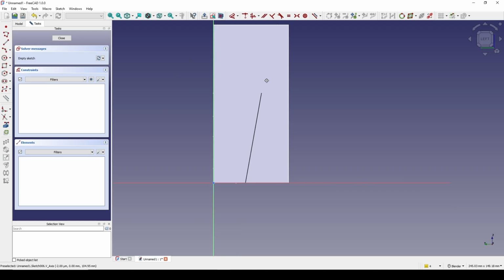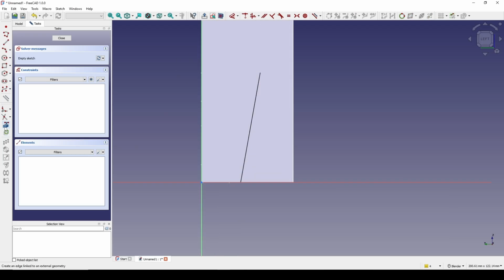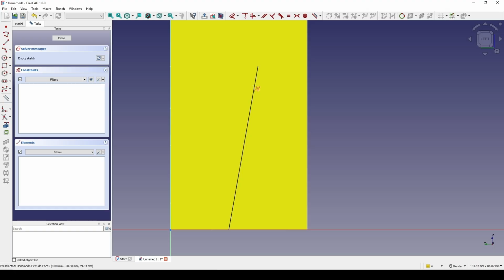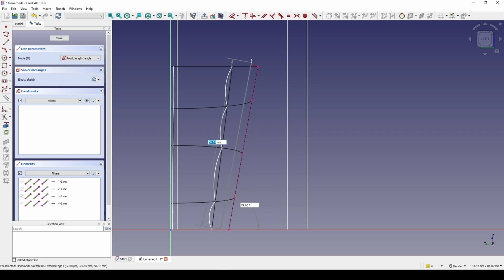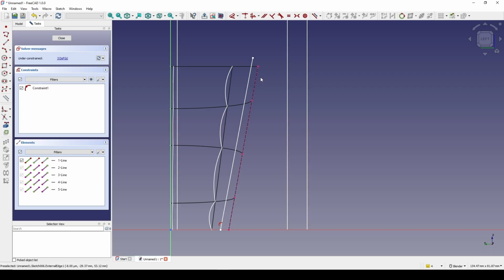View the section and I will reference. Sometimes it's hard to select the line. Okay, in this case, I just go to the wireframe to see the lines and reference not inside but outside these 4 lines. And then I can create a line parallel and hit P for parallel, and then insert a plane to show and turn that into construction.